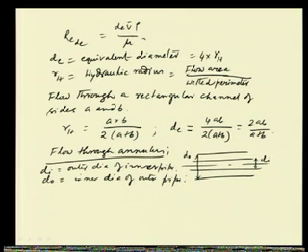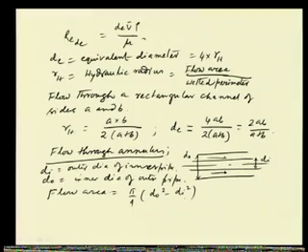Now, what we see in this case is that the fluid is flowing like this in the annulus region. In that case, the flow area is pi by 4 into dO square minus di square. This is the flow area of the fluid through the annulus region.